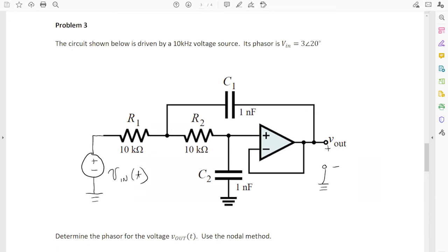Yeah. So this is okay. Good question there. Anytime I've got different points connected to ground, the implication is that all these guys are connected to each other like that. It's a shorthand way of saying if it's grounded, we often don't draw that whole wire.